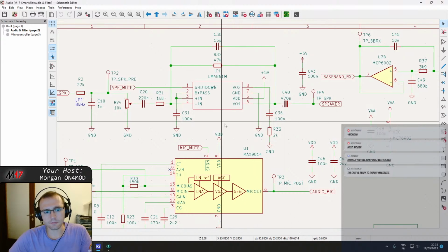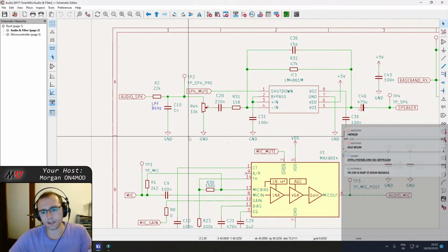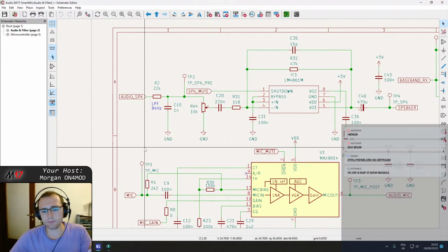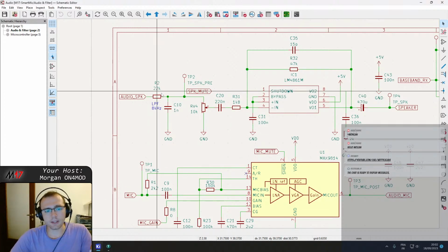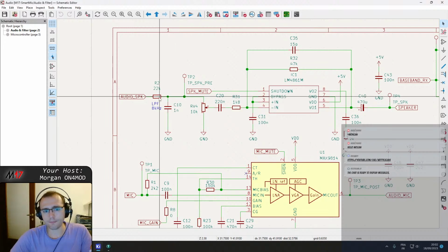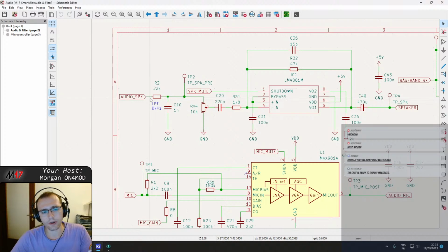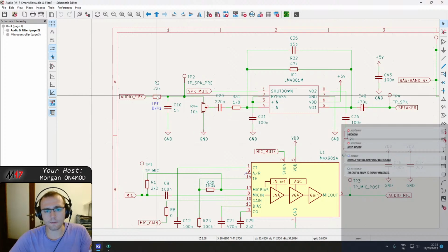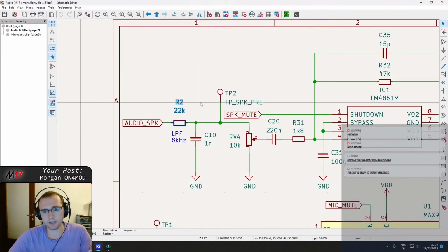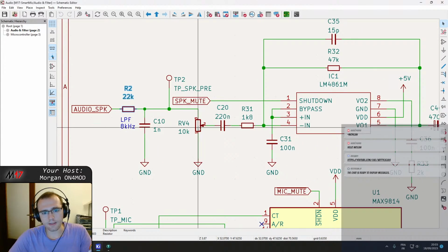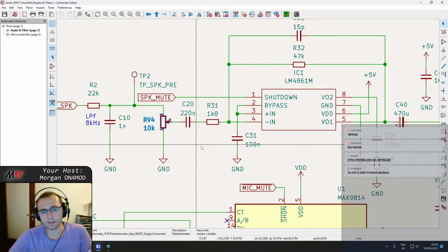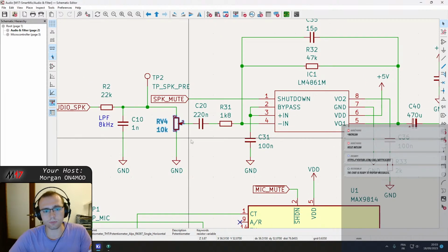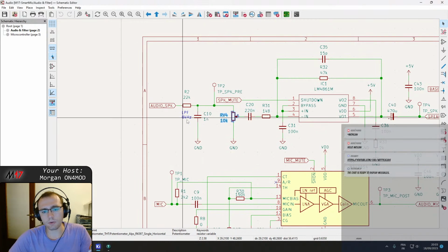This is going to change a bit. We are also going to change the low pass filter because we want another architecture. This is a passive filter based on resistor and capacitor. The problem with that is that the impedance of the filter is not constant across the spectrum range, and also it's at least 22 kilo ohms, which is a lot. Then we have this, which is used to set the gain of the amplifier, so basically the output volume.